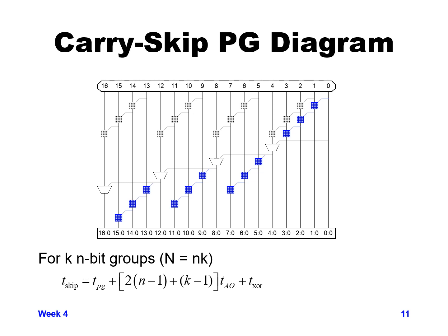So 14 plus 7 would be 21 and/or functions instead of 64. You can see where that, in a 64-bit adder, you'd get almost a factor of 3 better in delay timing through it. So as you get larger and larger adders, this has a great benefit. For smaller adders, it's not.